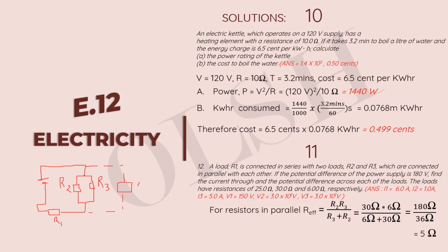Okay, which is 5 ohms, and we'll have exactly the same effect in this circuit as if we have these two here. So if we remove these two and put in 5 ohms here, it will just be the same thing. Having done that, we will now find the effective resistance in the circuit by adding R1 to the 5 ohms we got.